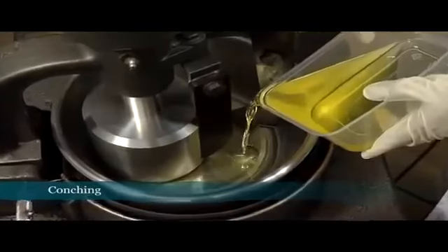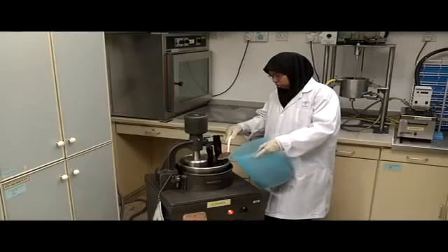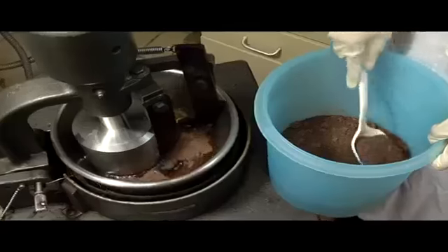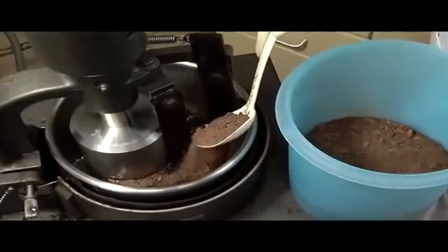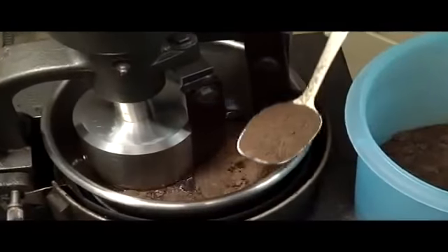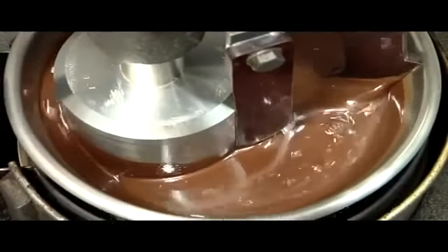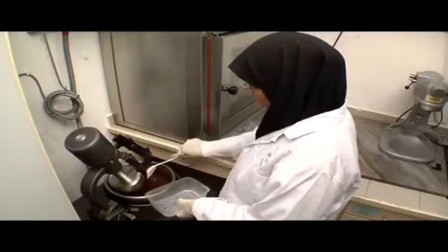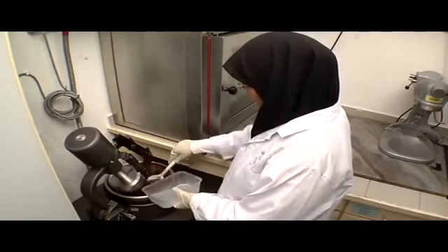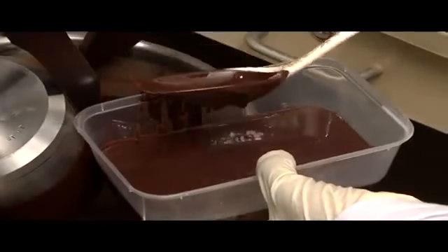Conching is a decisive process to produce good quality chocolates, as physical and chemical changes occur for the development of flavor and flow properties. Temperature control is between 65 to 90 degrees Celsius for plain chocolate and 50 to 65 degrees Celsius for milk chocolate. The duration is dependent on the composition of the mass, but it is normally more than 3 hours and often longer for plain chocolate. A homogeneous product mass is produced in the homogenizer.